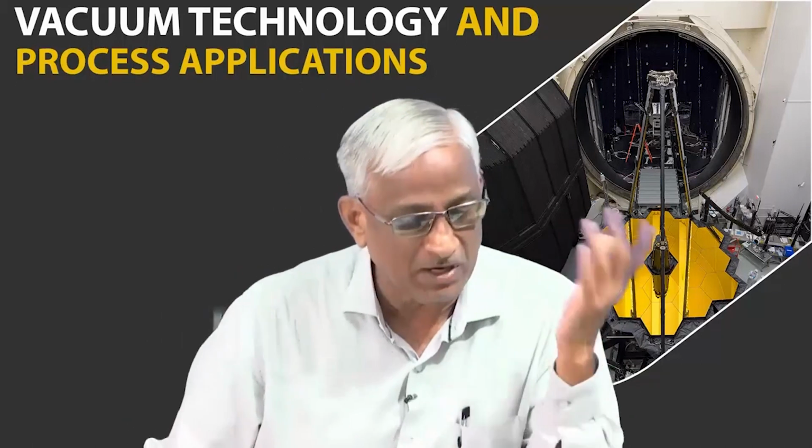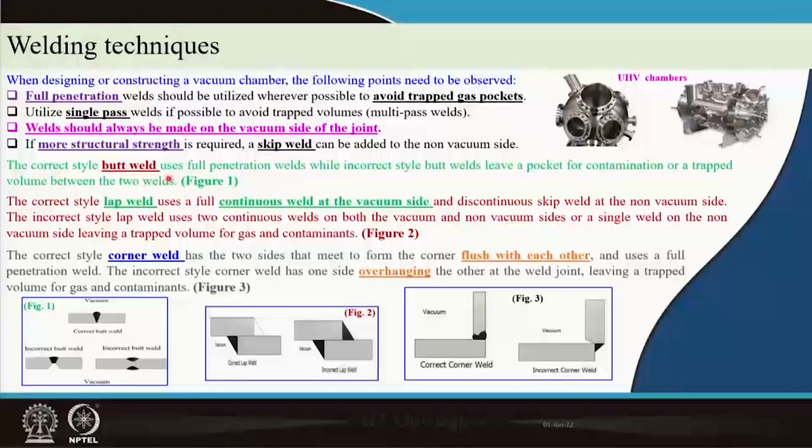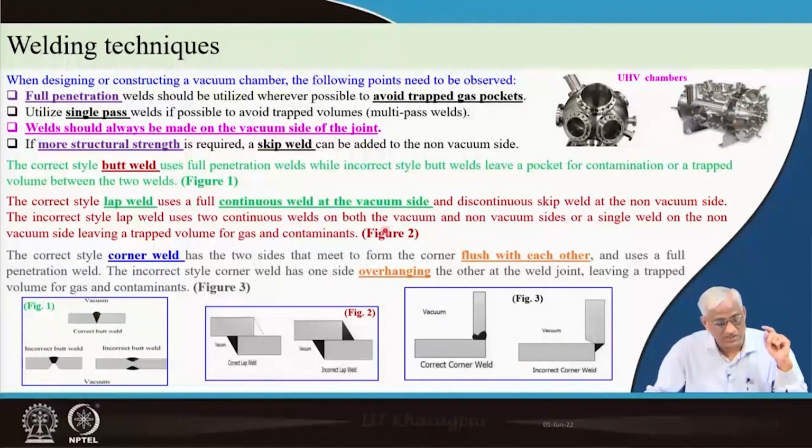of these things before welding, then you decide whether it is a butt weld or a lap weld or a corner weld. Okay. So, if it is a butt weld, full penetration can take place like this, that is correct welding, whereas a discontinuous penetration, that is very bad. Sometimes a pocketed gas may be there, it may be micrograms, but at 10 power minus 7 torr it creates trouble. And for increasing strength you are trying to weld on both sides like this, and if the penetration is not full, there is a small gap